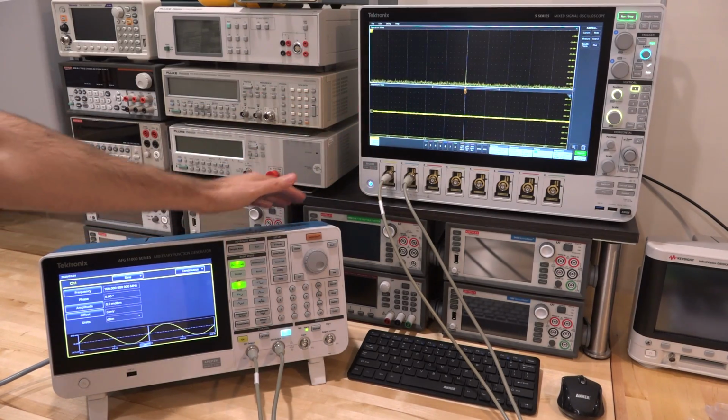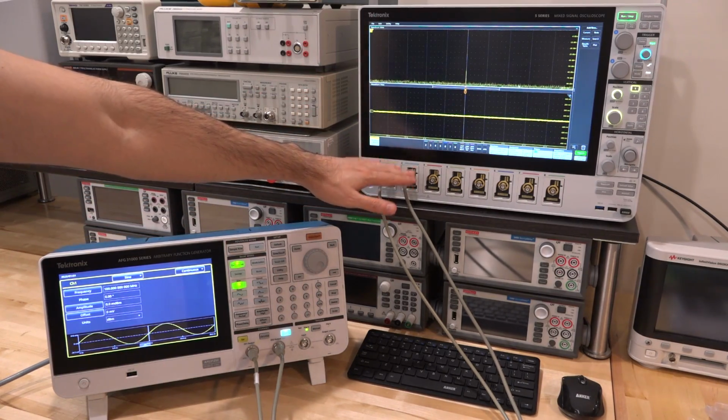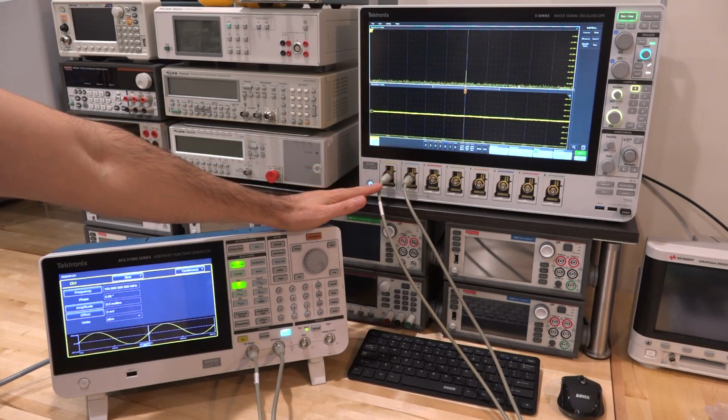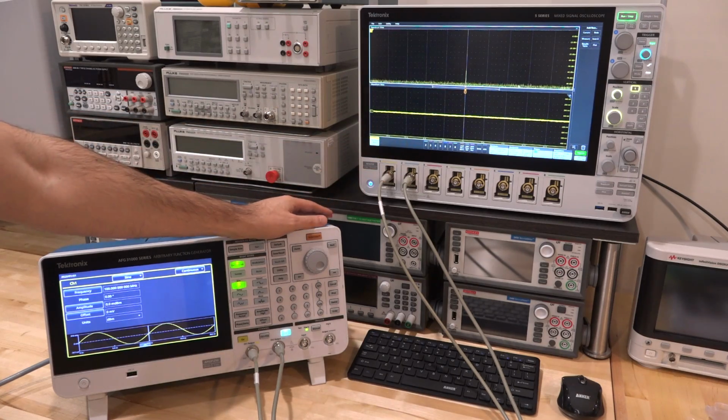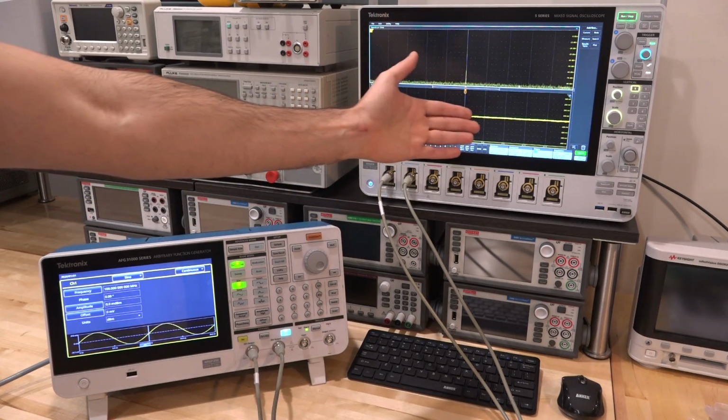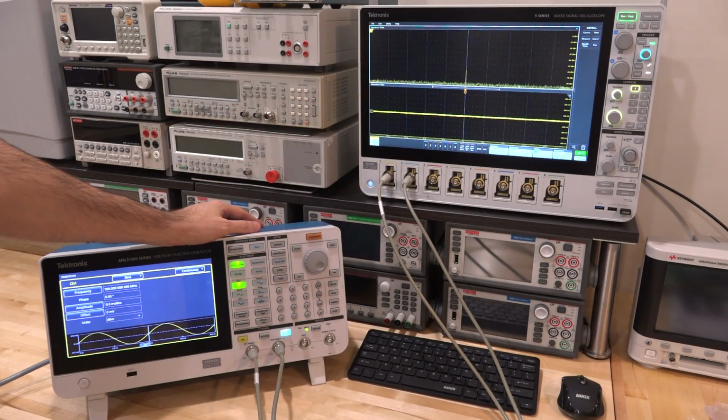The reason we do this is because we can trigger on channel 2, and that allows us to not trigger on the channel we want to look at the signal in the time domain. So we don't have a trigger line in the middle of the screen, which allows us to look at the signal across the entire screen and see how AM, PM, and FM modulation actually look.